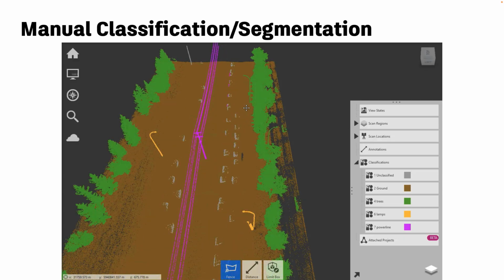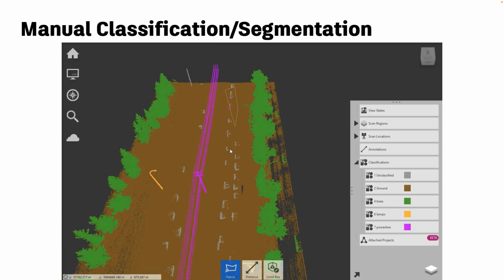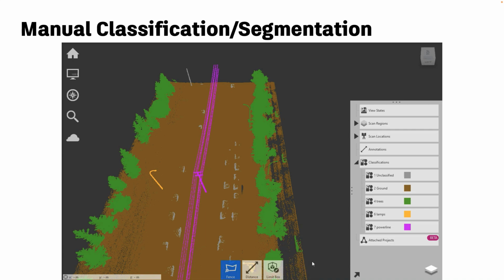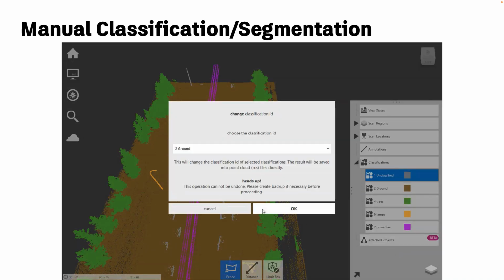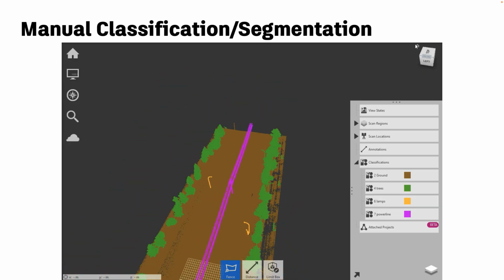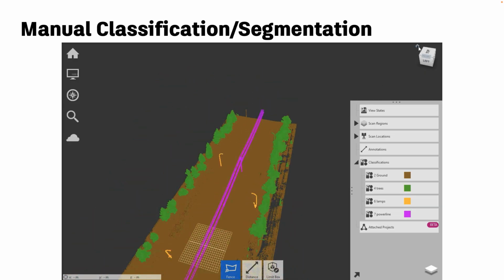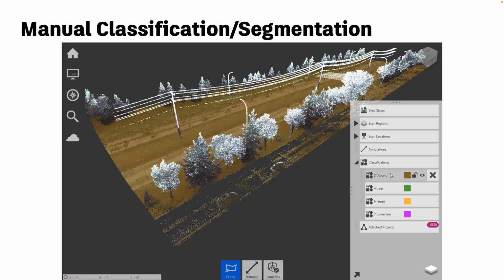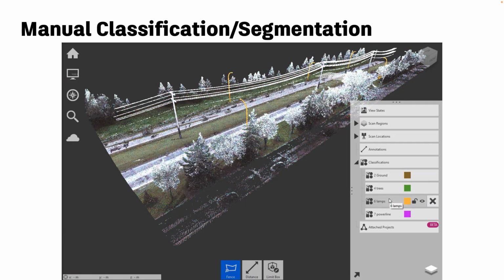This is obviously only possible because ReCap by itself can handle the point clouds more easily, more sophisticatedly. Right there, I can select it and classify the cars, and I can remove the cars, take them off my view, and I can see only what I want to, making visualization and other aspects much easier. So this is one of the additional cleanup tools you can leverage in the step 1 I showed you before, to take it forward.